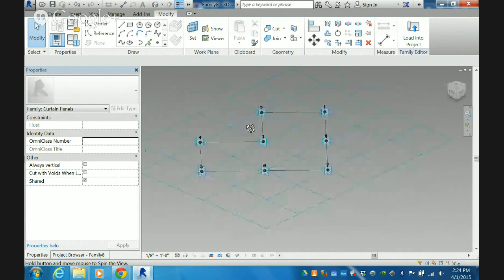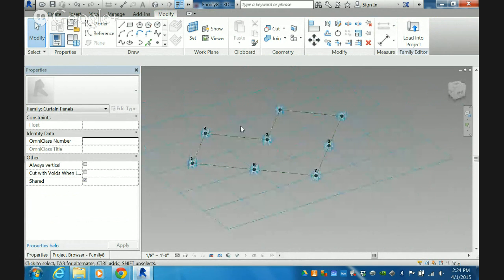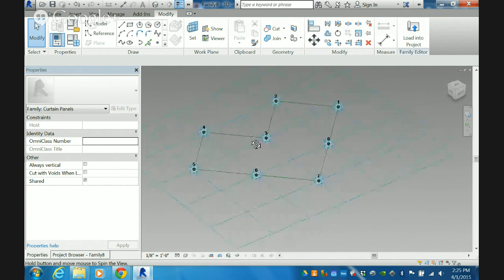So let's start working with this guy. Now, from inside this area, there's all sorts of little modeling tools and mass modeling things. What I'm going to show you in here is a technique from mass modeling that's particularly effective as far as adding parametrics to it. One of the things to understand is it really revolves around the use of nodes and lines to help create the forms, and then of course that's the skeleton that I talked about last time that we can start applying dimensions and things to. So let's start with a series of nodes.